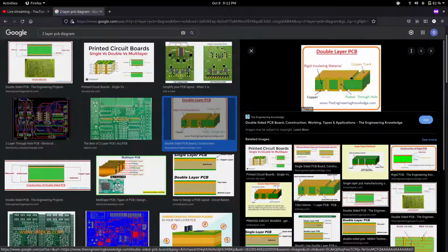But I digress. Top layer is copper, middle is FR4 usually, which is fiberglass, it's insulating, bottom is also copper. So that means that you have 2 layers in which you can have electrical signals. You've got the top copper layer and the bottom copper layer. Very often, because lots of things need to connect to ground, and also because you might have a lot of current being sunk through ground, the entire bottom layer is just grounded. It's called the ground plane. If you've got a PCB with more layers than this, like a 4-layer PCB, you might also have a power plane that brings in power.